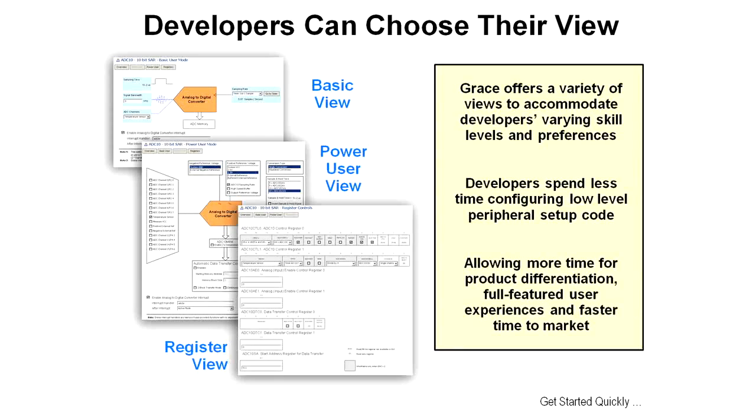We want to configure the A to D converter, so we want to tell it things like the sampling rate. We want to tell it the signal bandwidth and which ADC channel we're talking to. And then we're checking whether or not we want to enable the A to D converter interrupt. We tell it what interrupt handler we're going to use, and we're basically done.